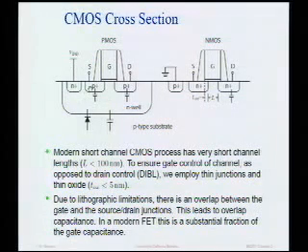In a PMOS device, I can just connect source to my body, and as we'll see, that effectively turns off the body effect. But in an NMOS device, I don't have that option. Because this is a reverse bias junction, I have to ground all my body nodes. That means that if I have source nodes which are not grounded, I will get the body effect. We'll see that later on. In a modern process, what we call a triple well process, you can actually put the NMOS device also into its own well and then ground the source and body nodes and get rid of the body effect.